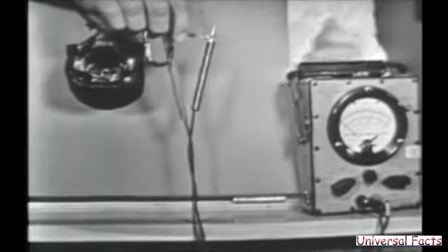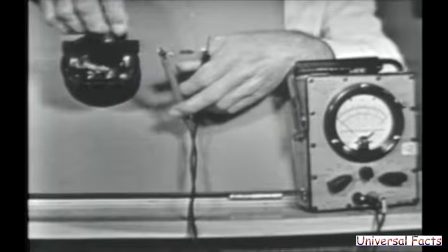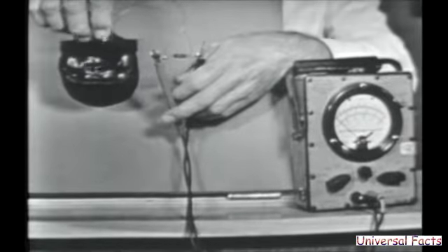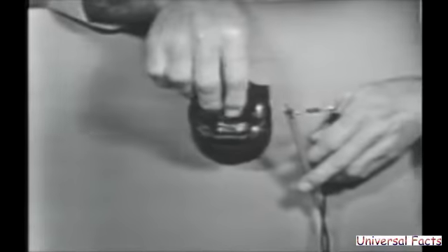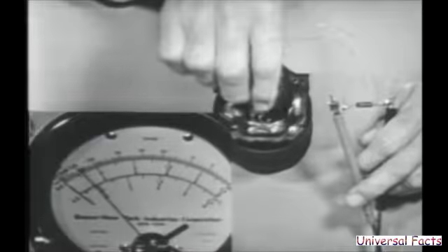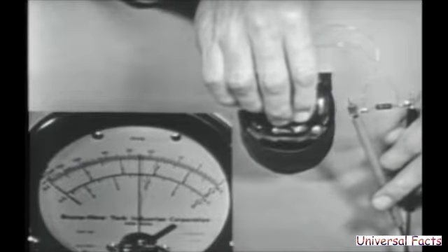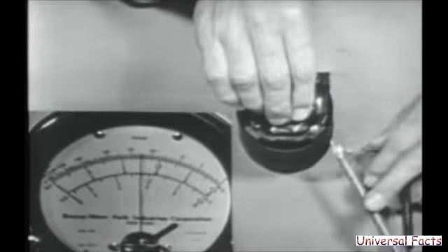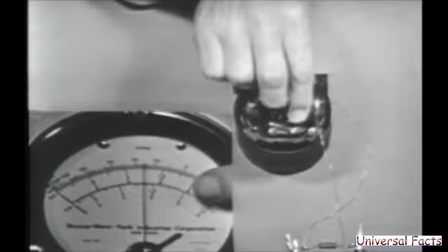Now, let me apply the juice first. You may hear a little hum being picked up by the microphone because of this magnetic field. Now, as I place this loop of wire into the field windings like this, you see, we've got something there. There it is. You see the PSM6 indicating a voltage value. That's induced voltage. That's right. That's the induced voltage from this loop.